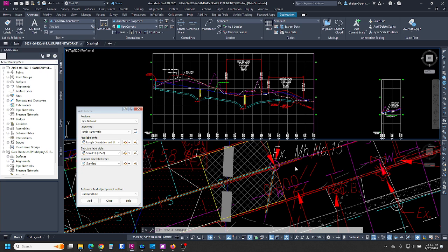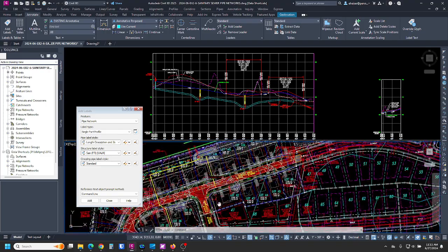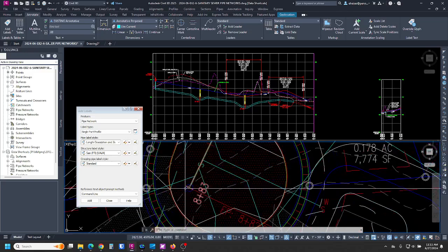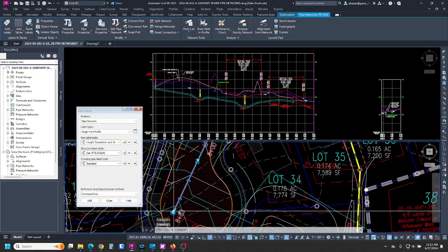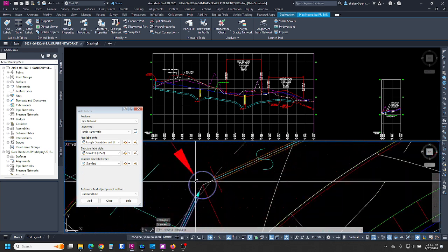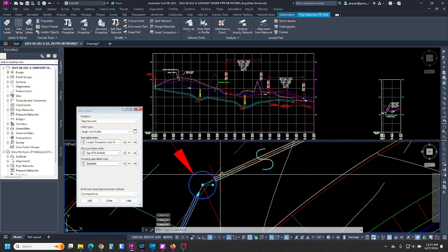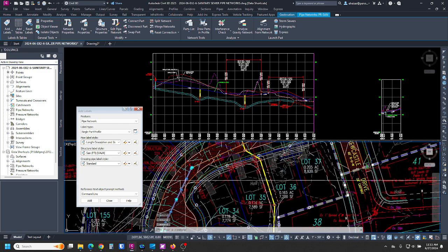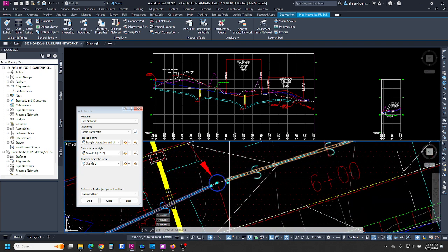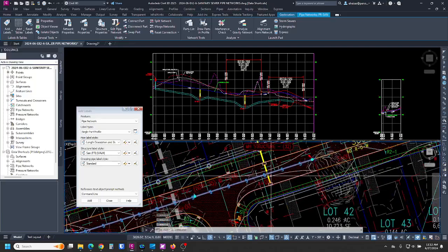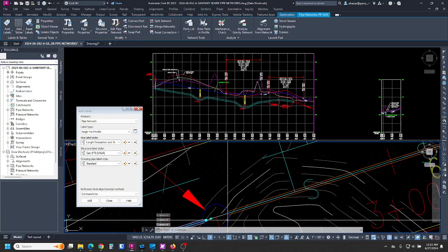So the way we are going to do that, there's a couple different ways. The way I typically like to do is selecting objects that I want to show. So just select a few of these and say we're going to say draw parts in profile view.